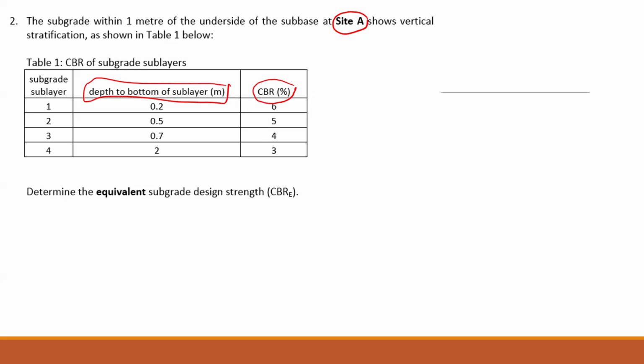The first part that we need to do is evaluating the subgrade and finding this equivalent subgrade CBR. When you consider your subgrade, you have done soil, am I right? Have you done that proctor test in a practical, where you are dropping a weight? You have realized that the number of blows that you need for different layers will be different because the CBR value will be different.